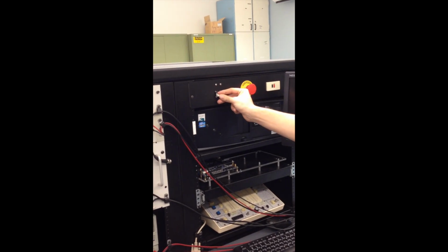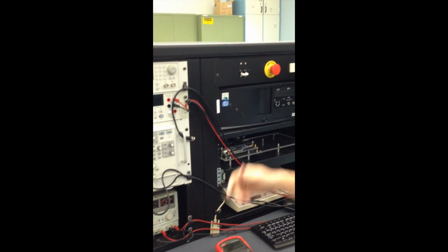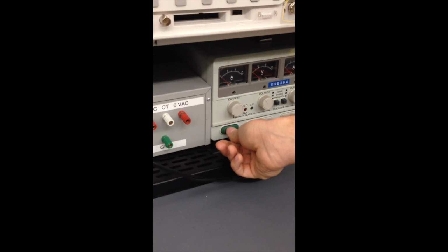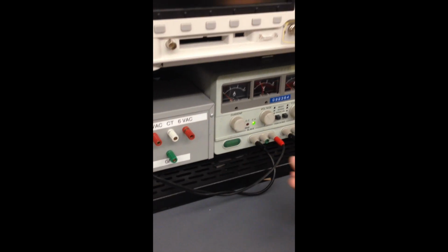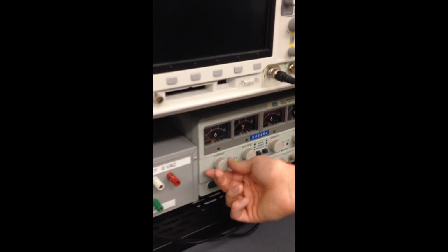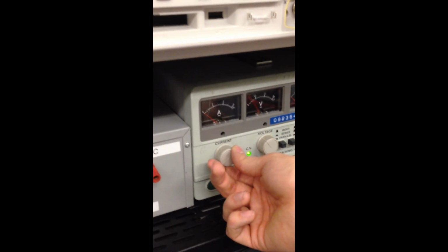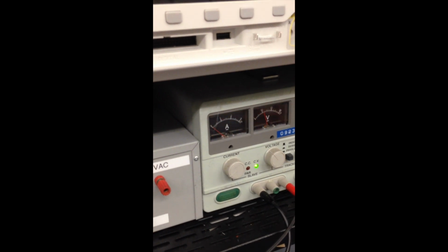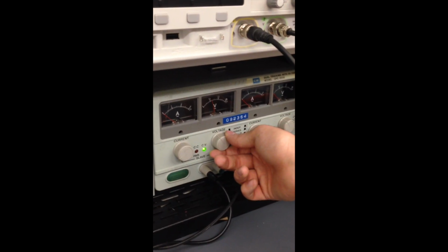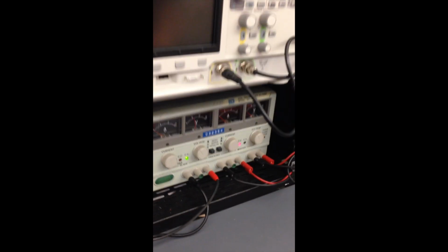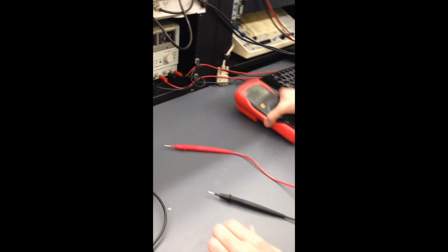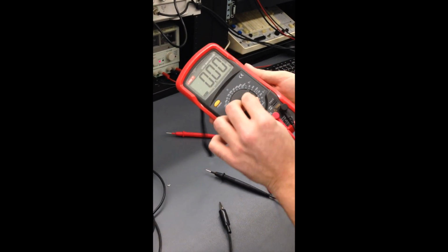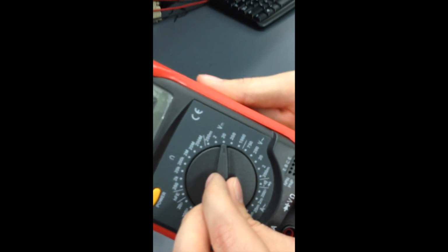The first step in building our RC circuit, we will turn on the individual power source for the workbench we'll be working at by pulling the lever down. And then we will turn on the power source for the circuit by pressing this button. Now, you want to make sure that the current is high enough so that the green LED here lights up. And then to toggle the voltage, you use this dial. But first, we will connect our multimeter here, turning it on, and setting the dial to 20 volt maximum.